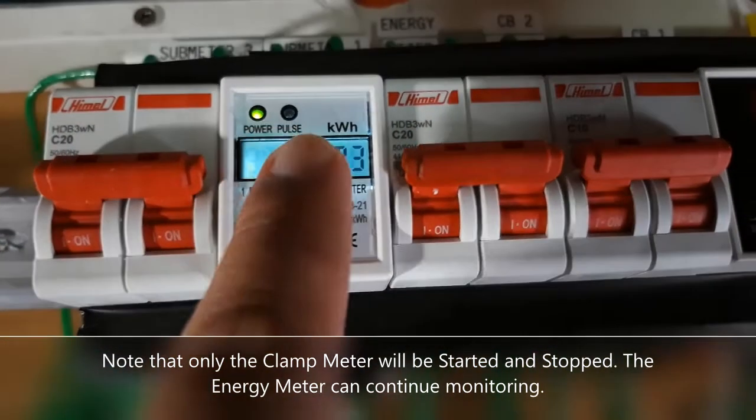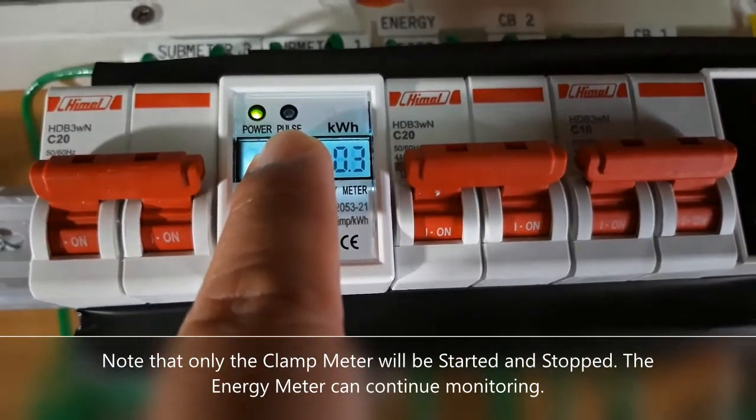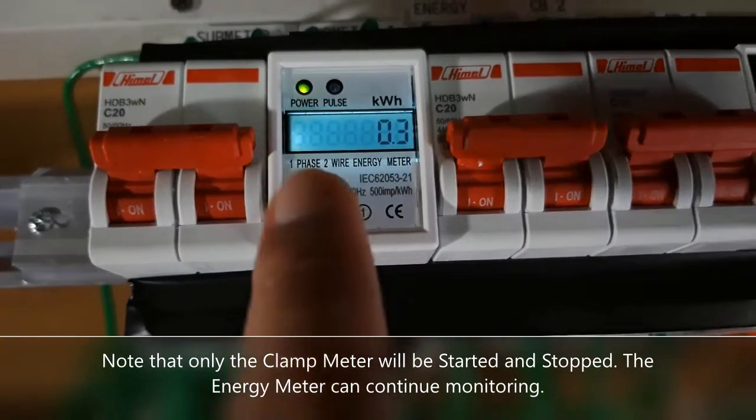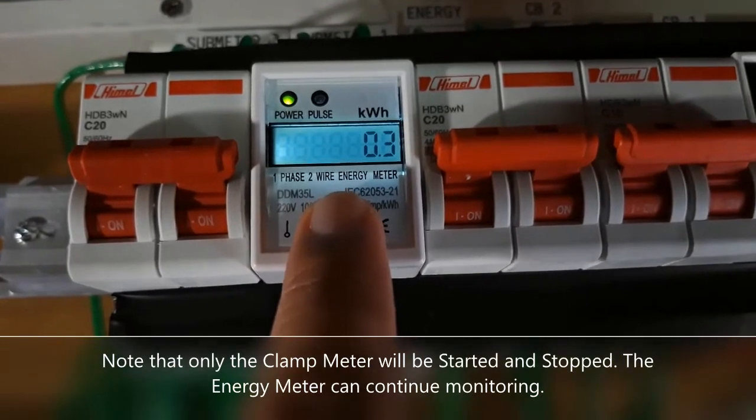So we will start our measurement on the clamp meter when we see the pulse light up, and then we will stop the measurement when this pulse lights up again. So that's how we synchronize the energy measurement between the two meters.